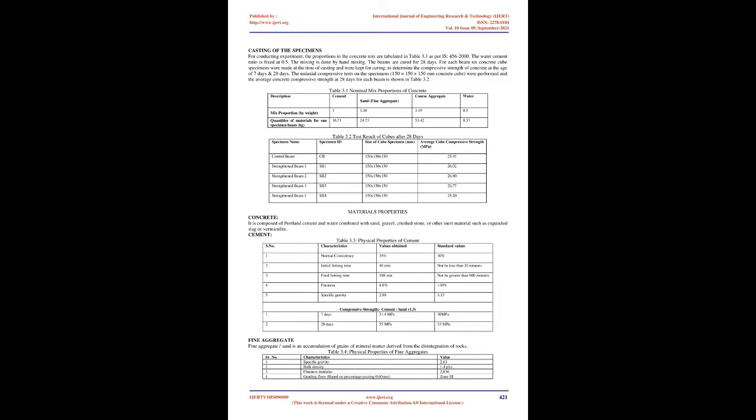Types of FRPs. There are three types of fibers that dominate. These are carbon, glass, and aramid fibers, and the composite is often named by the reinforcing fiber. Carbon fiber reinforced polymer, CFRP. Carbon fiber reinforced polymer is a material consisting of extremely thin fibers about 0.005 to 0.010 mm in diameter and composed mostly of carbon atoms.